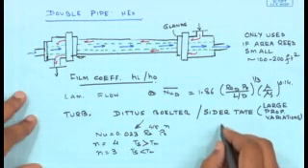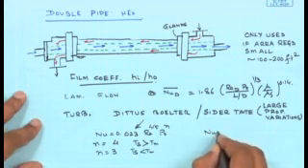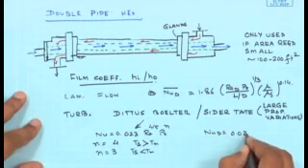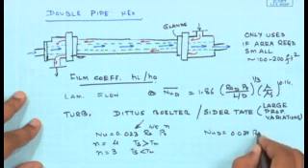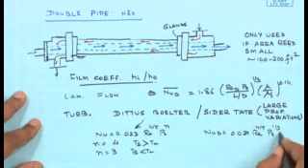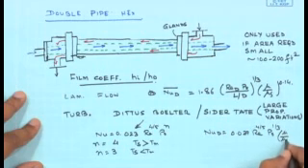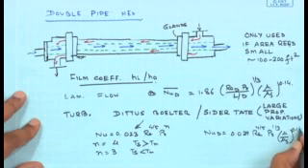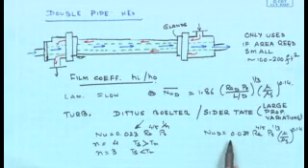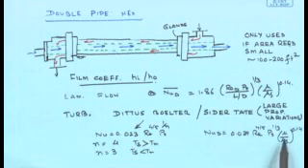And for the case of Sieder-Tate, the Nusselt number is simply going to be 0.027 Reynolds to the power 4 by 5 times Prandtl to the power 1 by 3, and the viscosity correction factor mu by mu s to the power 0.14. This is when you have a significant variation in the property.